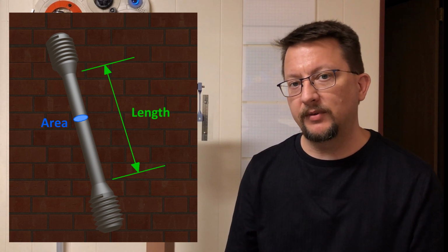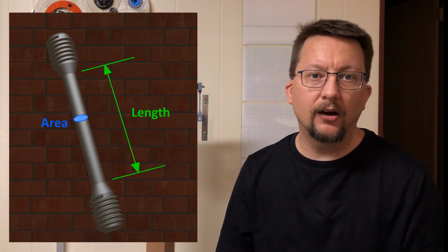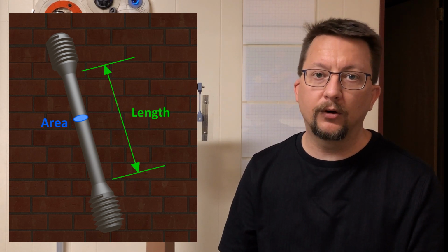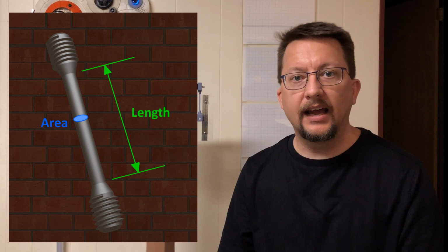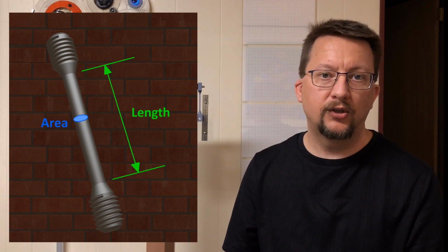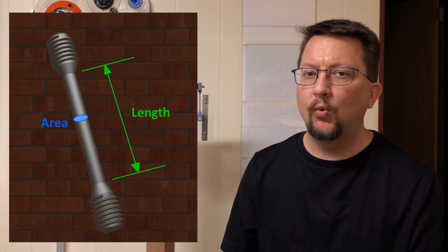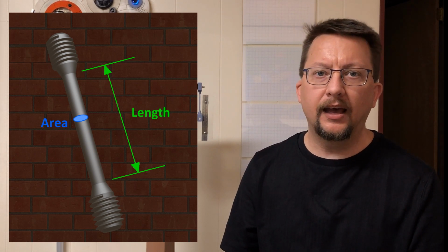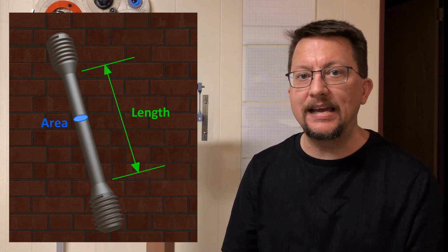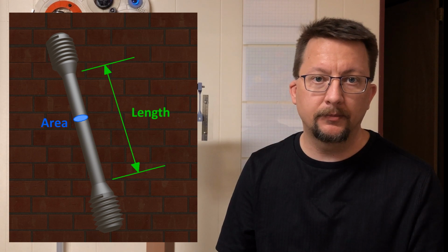So when we test steel, you design a sample that has a neck down area of a known diameter or cross-sectional area. And then there's also a known length of that thinner portion. So we can really identify, as we're pulling this in tension, what's happening in there, and we can watch and measure everything that happens, and then we can learn so much from that test.